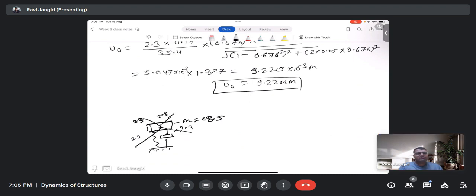Actually, in this calculation, the mass at the centroid and the mass of the blade are given to you as different; it is included as 28.5 plus blade mass. But I am thinking the equivalent mass will be different. Actually, it will not be the addition of these two, the blade and the motor. It will not be 37.7. This is from the practical point of view, because one mass is concentrated at the pivotal point, and the other masses are away from it by distance L or whatever.